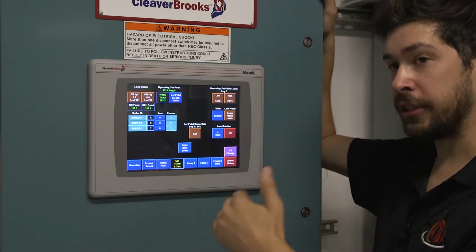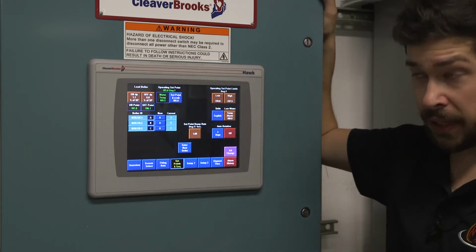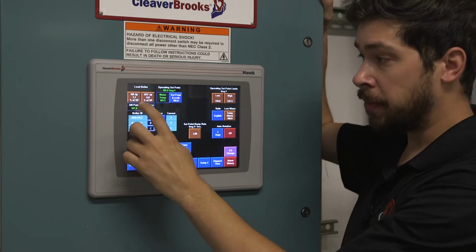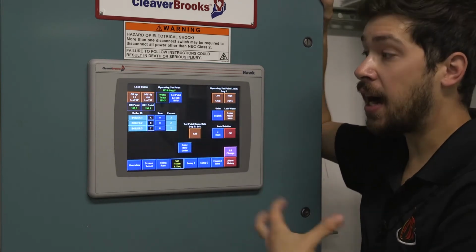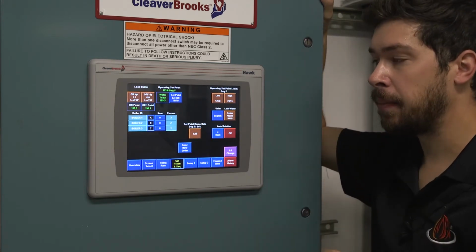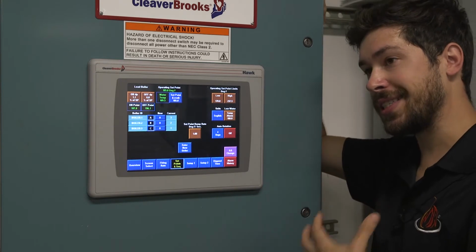At that point, 187, the boiler starts to kick on, and we start this looping cycle all over again. It's very important that the on point number is higher than your set point, because it helps reduce the cycles.